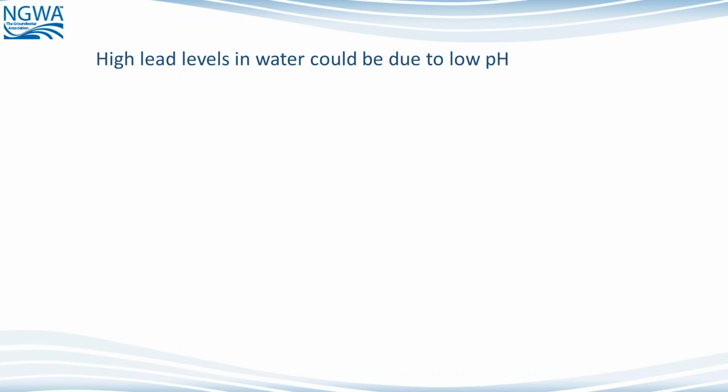One comment: a water softener in the home will not make water more corrosive. All it does is replace the hardness with sodium ion. So it's not going to be more corrosive, but if the water has low pH, or certain other chemical constituents in it, it could be corrosive.